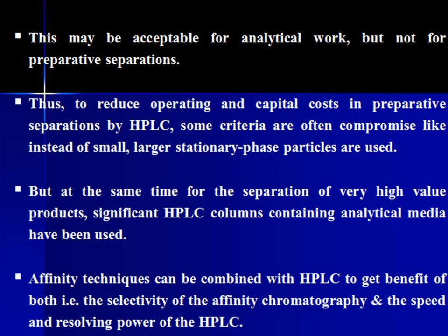This may be acceptable for analytical work but not for preparative separations. Thus, to reduce operating and capital cost in preparative separations by HPLC, some criteria are often compromised, like using larger stationary phase particles instead of small ones. But at the same time, for the separation of very high value products, significant HPLC columns containing analytical media have been used. Affinity techniques can be combined with HPLC to get the benefit of both, that is, the selectivity of affinity chromatography and the speed and resolving power of HPLC.